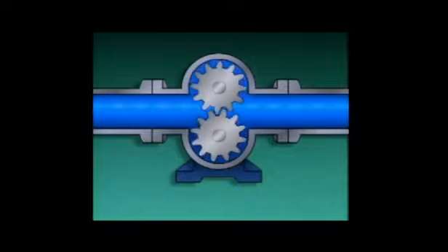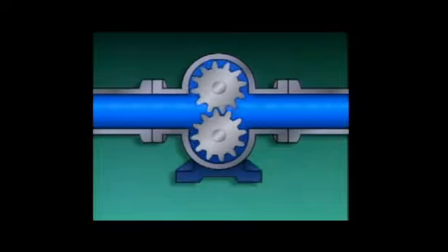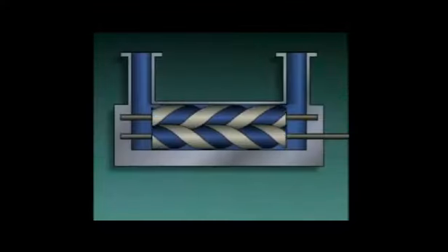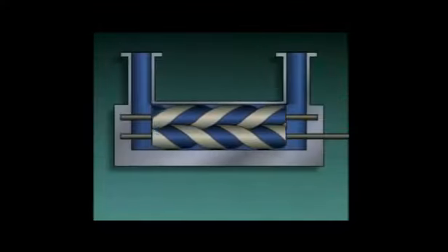On this type of pump, each space between the gear teeth positively displaces a given amount of liquid. So, on each revolution that the gears make, a specific amount of liquid is pumped. And this pump can be classified as a rotary pump.